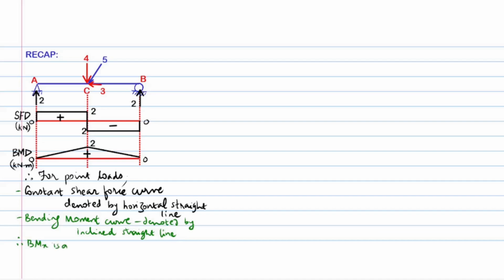We can therefore conclude that the bending moment is a function of x of power 1 more than that of the shear force. That is, mathematically, the derivative of bending moment at any cross-section leads us to the shear force at the section in general. Or the integration of the shear force leads us to the bending moment at the section in general.